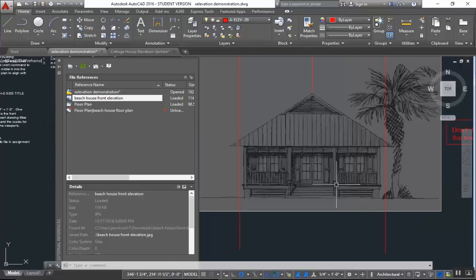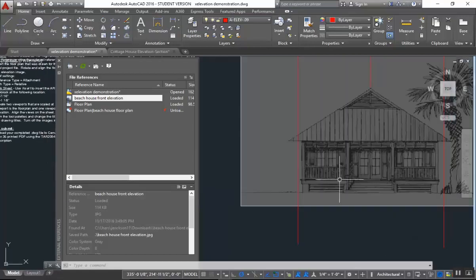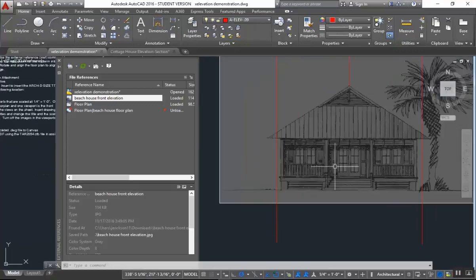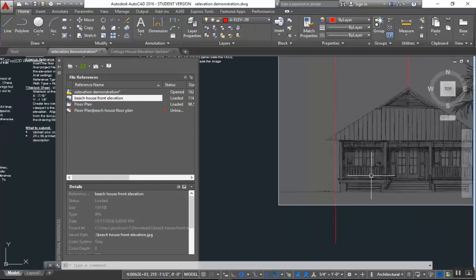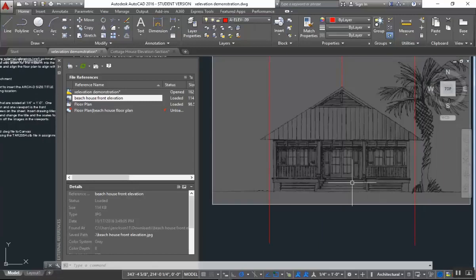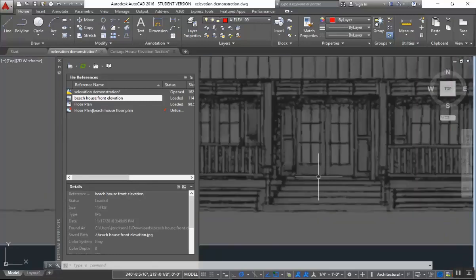All right, so in an elevation view, we have two primary dimensions. We have horizontal dimension and vertical dimension. We call that width and height. So in this view, the primary dimension that we don't really see anywhere else is the height. It's elevations. So it's vertical dimensions. So in an elevation, the primary elevation is the vertical heights. And the datum that you use to be the 0 point is called the finished floor elevation. Finished floor elevation is the bottom of the door in this case.